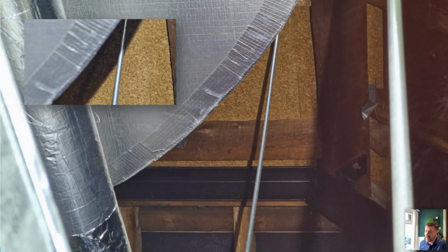But if you come across it from the top, and you couldn't see it from the underside when you're doing a core sample, which we do from time to time, as sometimes you can't see the underside, the only way that you're going to know it's a chipboard deck is by taking that core sample. Just be very careful, especially in areas where there's been water ingress, because this stuff really does go like Weetabix and can be structurally unsound if you're trafficking the roof.